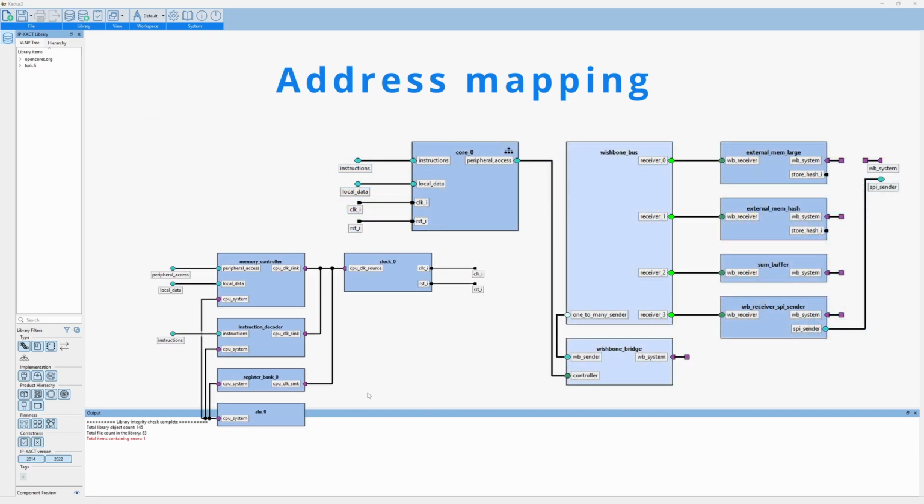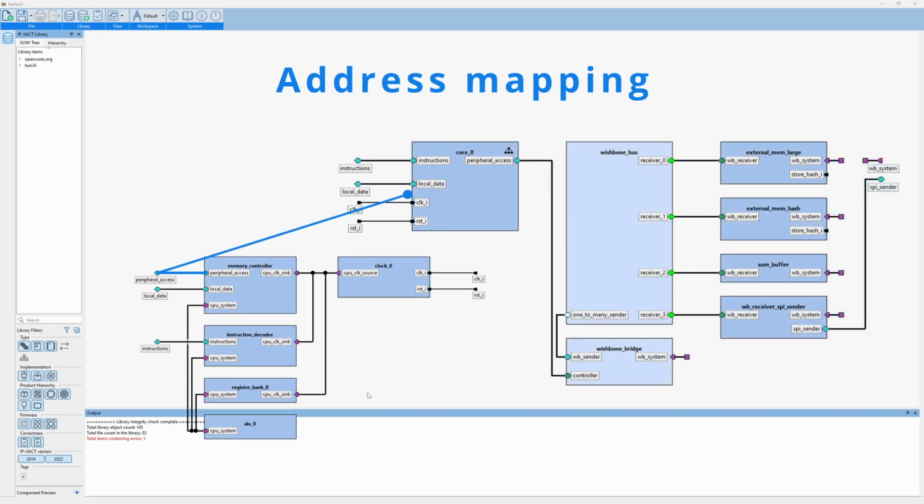Final mapping of the register is resolved by traversing from the address space to the connected memory maps, following all the address transitions made by the connected components in the bus interfaces along the route.